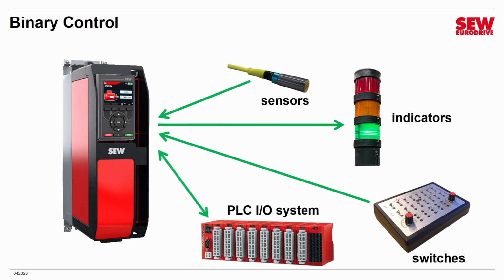If you really want to get sophisticated and interface a terminal control application to a PLC, you don't have to do anything fancy like hook up a field bus. You can just wire the PLC's I/O system directly to the digital inputs and outputs. So terminal control mode is sometimes actually used in a very sophisticated way by interfacing to a PLC. Never forget that that opportunity is available to you. Just remember, whatever you do, be sure that you have 24-volt compatible logic, and as long as that's true, everything should talk and play nicely.